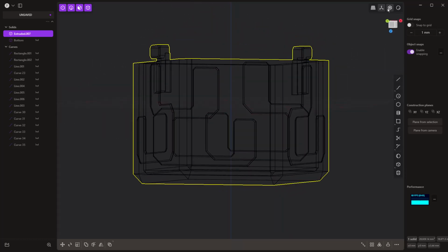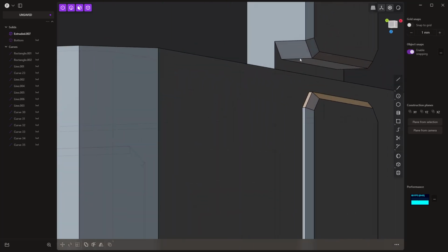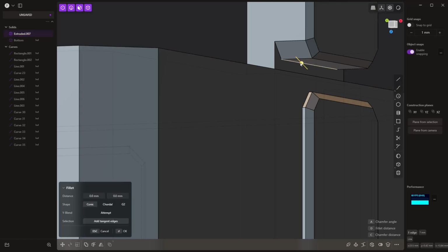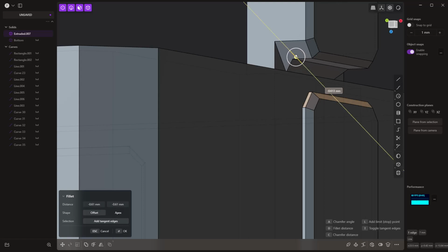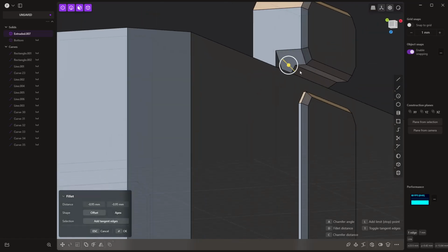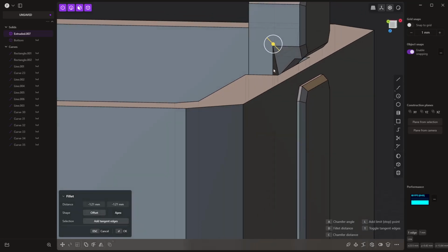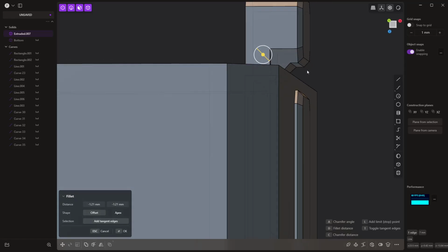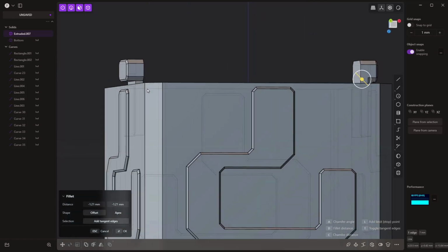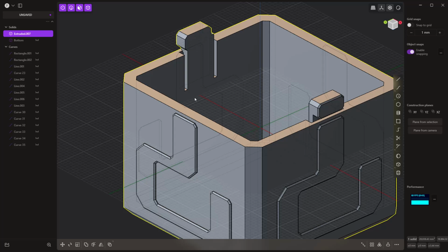these away. Another thing that we need to consider, and I'll bring the faces back for this, is this bottom edge is basically hanging out in space. Printing that is going to be difficult. So we probably want to either add some sort of chamfer there or add something else that allows us to print that a bit easier, because this is going to be an overhang and that is problematic. So make sure that we just add some geometry. We don't want it to overlap, but that will probably give us enough to print there. I'm going to go ahead and pull this over, hold down Control and select that one as well. And now we've got our push buttons.